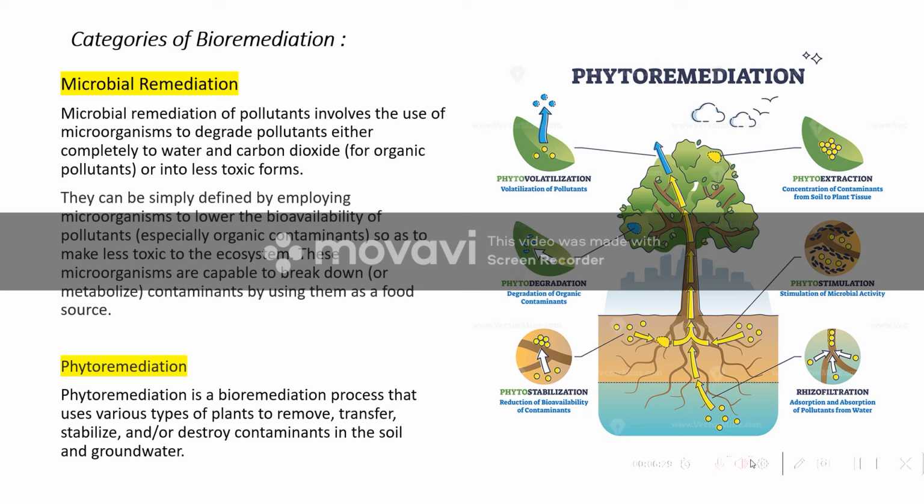This method of growing can be used for ex situ groundwater treatment. That is, groundwater is pumped to the surface to irrigate this plant. Typically, hydroponic systems utilize an artificial soil medium such as sand mixed with perlite or vermiculite. As the root becomes saturated with contaminants, they are harvested and disposed of.